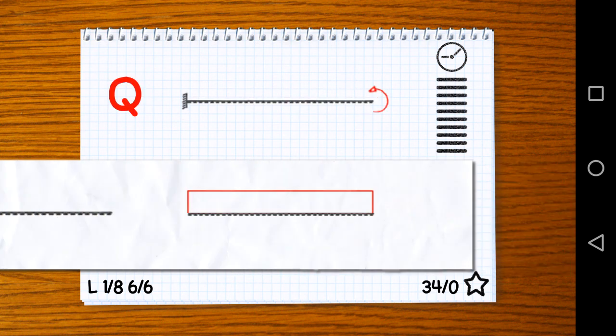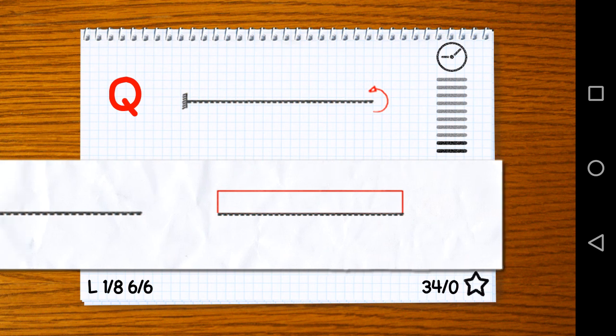Now the distribution, the function, is due to the fact that the loading was a constant load, so it's a quadratic moment. So here, shear forces. But what do we have as a loading? We have a single moment. That single moment is going to go directly into the clamped support. The clamped support is the only support here that can take that moment. So in this beam, we only have a moment distribution, but no shear forces.